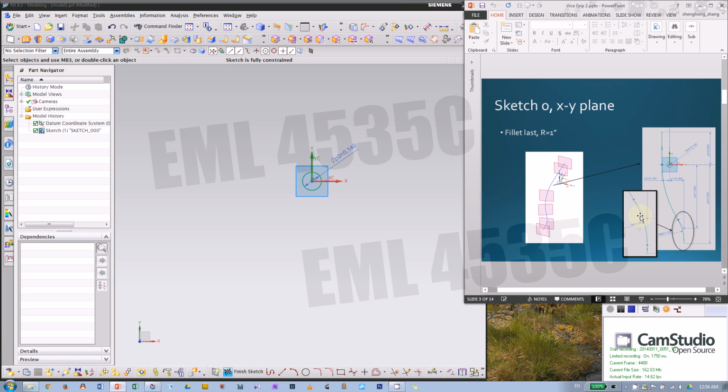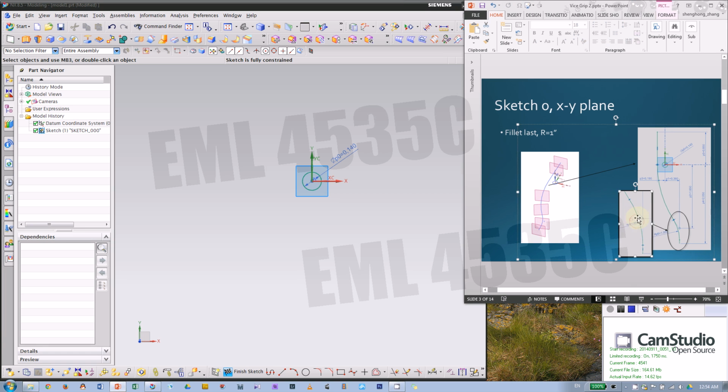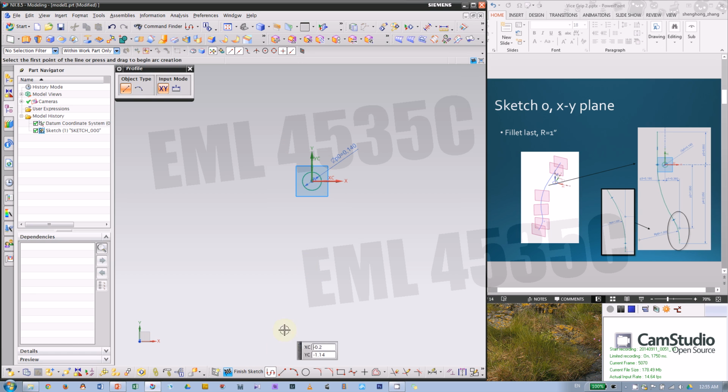If you look here, this little zoomed-in picture is actually the fillets. That's why you get this point here, because that was a corner before I made a fillet. So this gives me some idea of how I made this. I made this straight line, and there's an arc connecting both of them. We can use the profile tool, or you can use a straight line here, a line there, and a 3-point arc. That's one way, and make the top corner tangent.